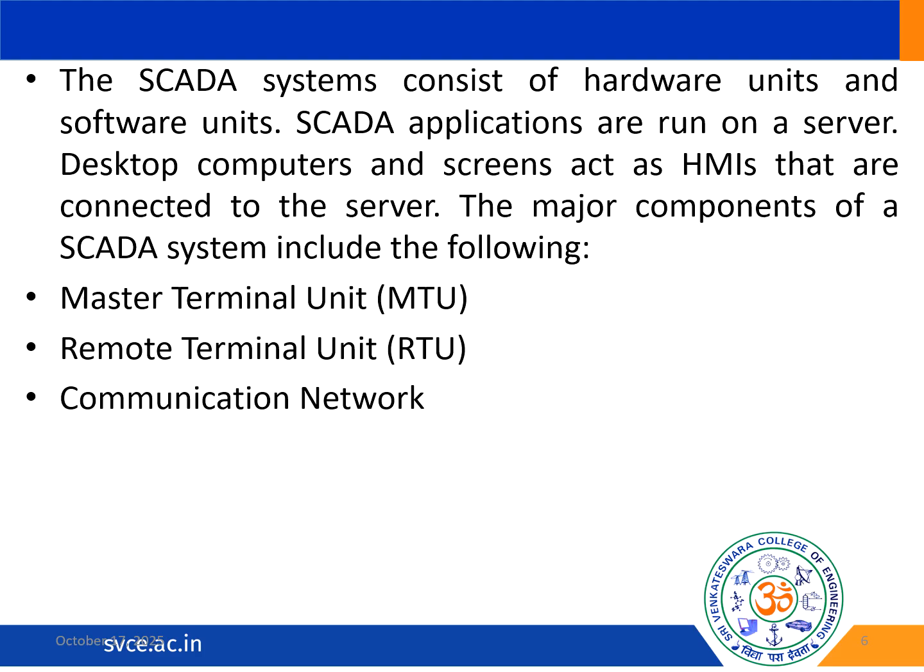SCADA applications typically run on a central server, which handles data processing, visualization, and control logic. Human machine interfaces usually use desktop computers with graphical displays. They can be connected to the server, allowing operators to interact with the system in real time.